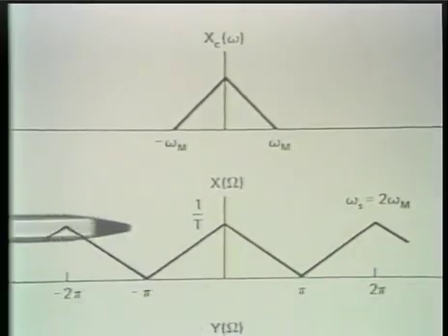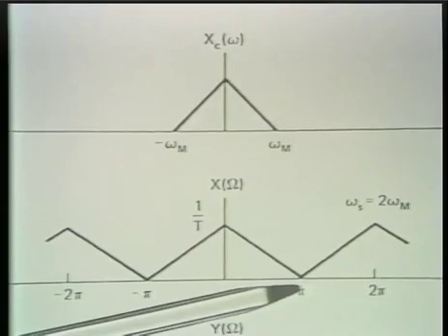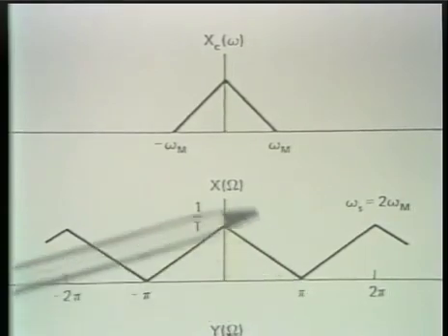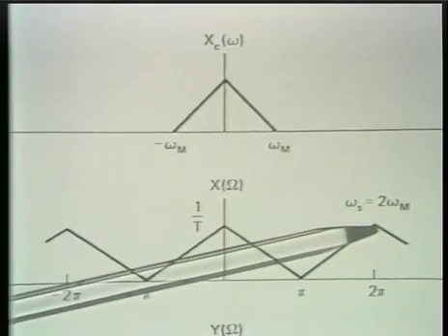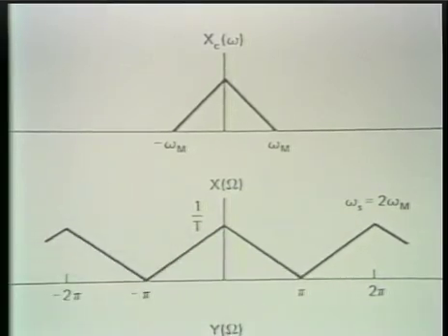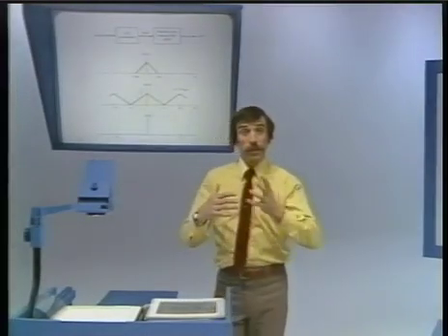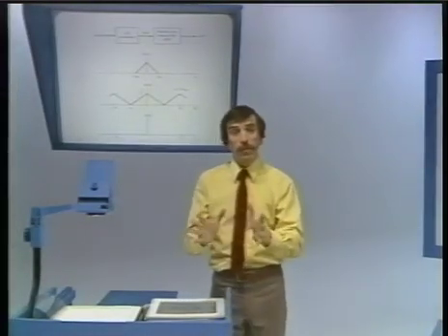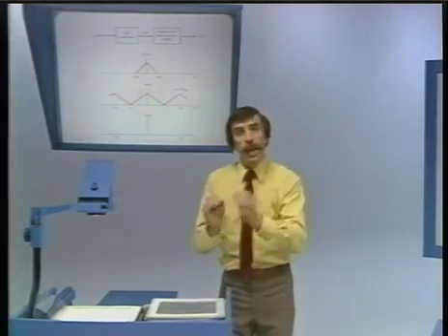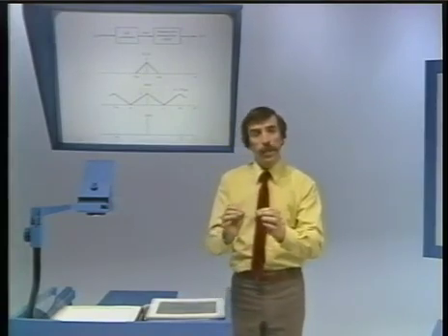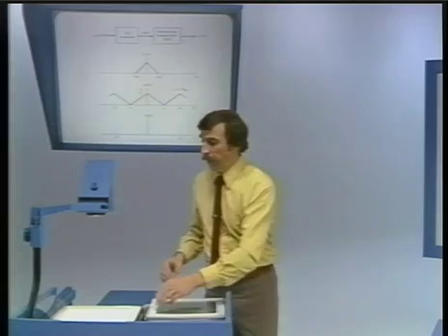And I've chosen the sampling frequency to be just high enough so that I avoid aliasing. Well, that then is the lowest sampling frequency I can pick. But now, if we go through some additional low-pass filtering, then let's see what happens.